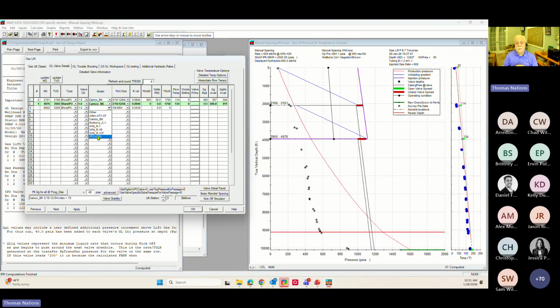We could hold the upstream pressure constant and flow through the valve while varying the downstream pressure, and then map the flow rate of basically injection gas through the valve, and then develop mathematical correlations for those descriptions.